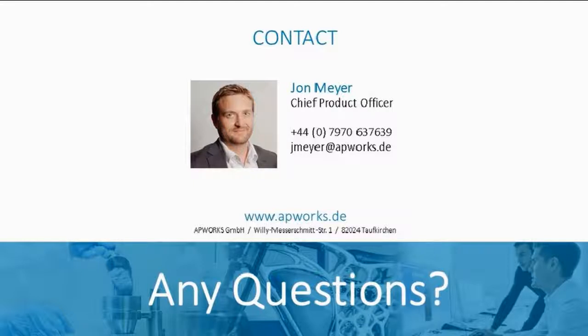Generally, it depends upon the alloy system. You have a different process dynamic with powder bed fusion, which is what we're talking about here. You have very, very high cooling rates in the process. That can be detrimental for some materials, but can be extremely beneficial for others. So the Scalmalloy example I gave is one where it's extremely beneficial.